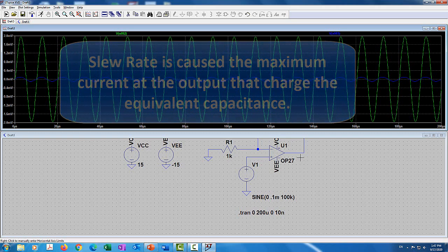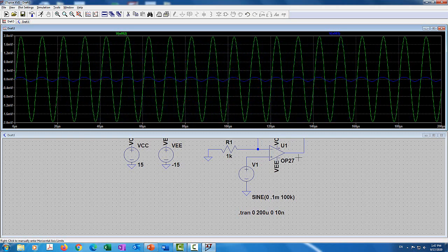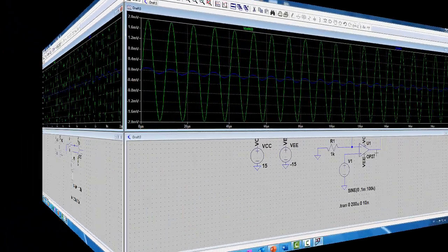It's basically the way the op-amp works. So frequency response will affect the gain. That will affect the behavior of the circuit. And then also you're going to watch for the slew rate, which is the maximum dV out/dt. Those are two important things that you need to watch when you design your op-amp as a function of frequency.